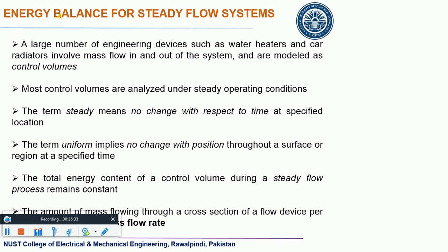Just a few things which you already know, but I would repeat those technical terms. Control volumes. Whenever you are to analyze some engineering system, in case of fluid mechanics or heat transfer, you consider that system to be the control volume. You remember the free body diagram from statics and mechanics of materials courses? The same is the case with control volume in fluid mechanics and heat transfer. This is the system of your interest. You isolate it from the surrounding, apply all the energy interactions and just apply this equilibrium, energy conservation principle.